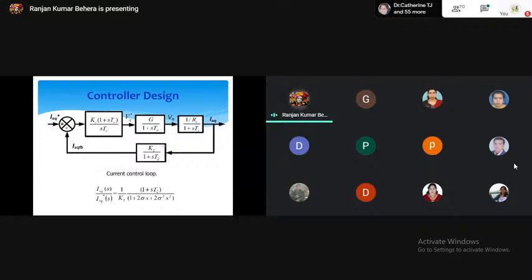And then we have in the feedback, you see K2 divided by 1 plus ST2. Why we introduce this one? Generally, in the feedback path, we have a unit gain. When you bring from output and connect to the input, it is 1. So that is called the unity gain everywhere. But here we put K2 by 1 plus ST2.